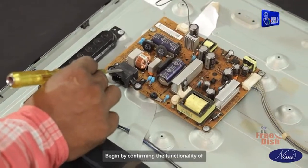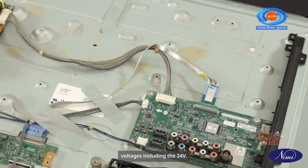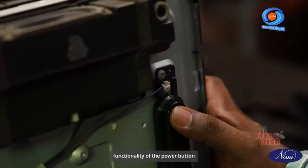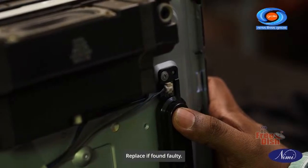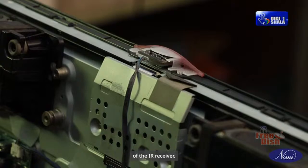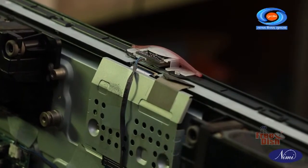Begin by confirming the functionality of the power supply board, ensuring all voltages including the 24 volt. If the power supply board is operating correctly, proceed to inspect the functionality of the power button on the front panel. Replace if found faulty. Next, assess the performance of the IR receiver. Replace if necessary to restore signal reception.